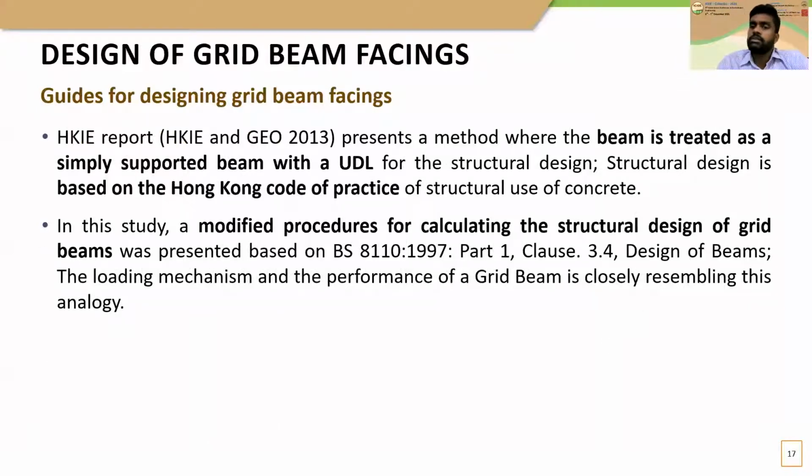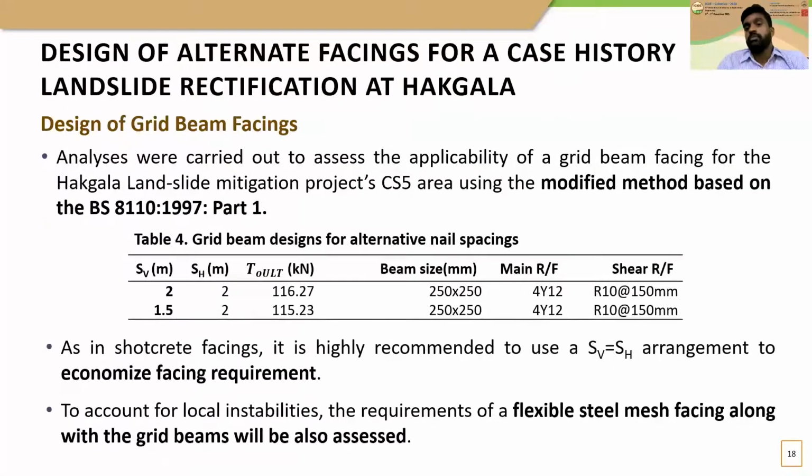The Hong Kong Institute of Engineers report for designing village structures is adopted in the study for grid beam designs. There, the beam is treated as a simply supported beam with earth pressures as a UDL. However, the structural design is based on the Hong Kong Code of Practice. As such, in the study, a modified procedure for calculation for structural design of grid beams was presented based on BS8110. Moving back to the case history, the proposed method was utilized in determining structural requirements of a grid beam